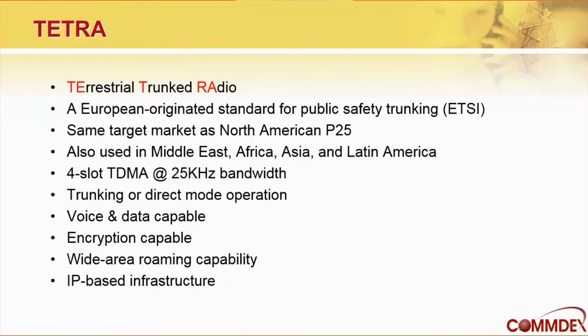The main thing that's different about it is it uses 4-slot TDMA, but in a 25 kilohertz bandwidth, which is why it's not being used in the US, because it requires 25 kilohertz bandwidth, and we're only allowing 12.5. It does it with 4 slots, so the effective bandwidth is still 6.25, but it wouldn't be allowed here because of its bandwidth. It can operate in trunking or direct mode,